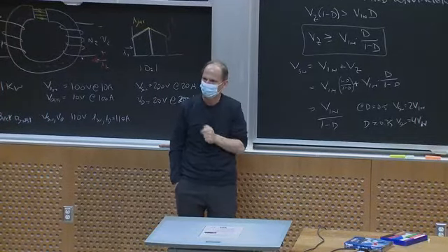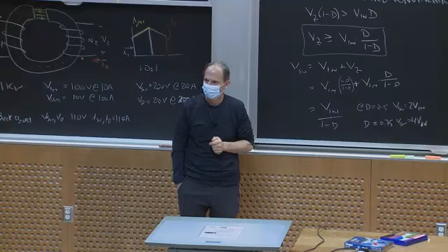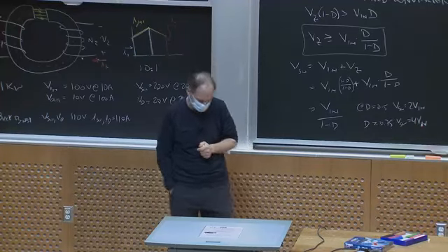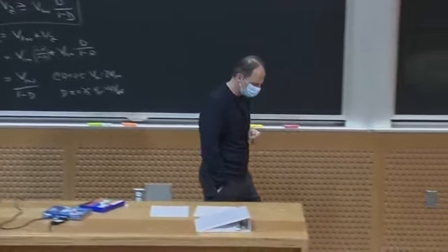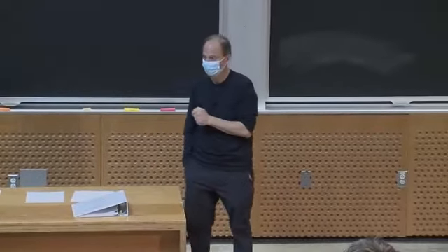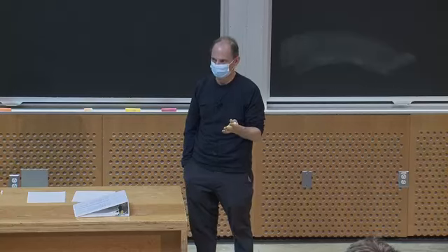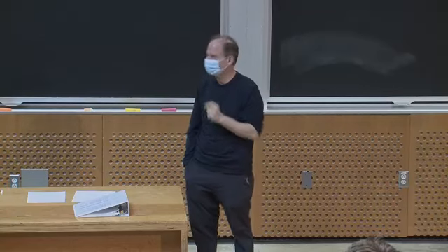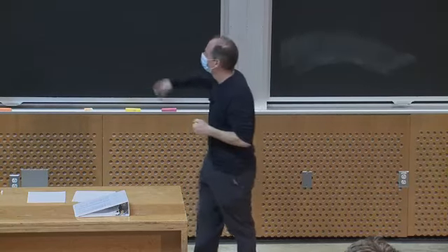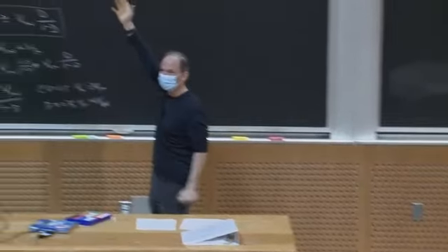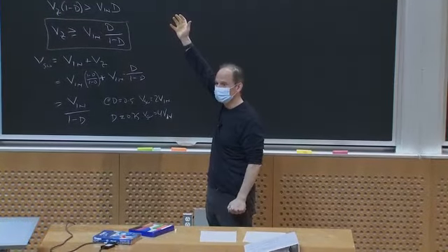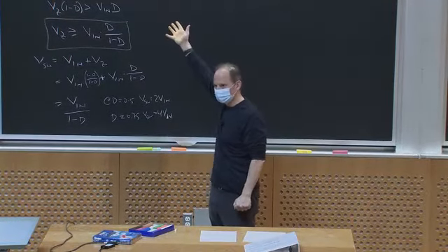Yeah, Jack? How would you use the forward converter over the flyback? Ah, that's a very good question. That comes back to, and we'll talk more about this, how big it is. So we're going to come back to this. But remember, a buck converter is a direct converter and has very low stress on its switches and low energy storage in its components.